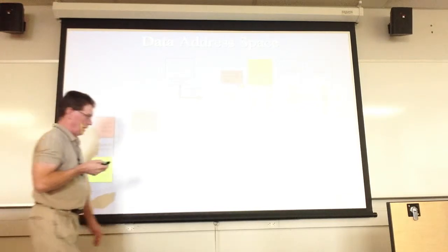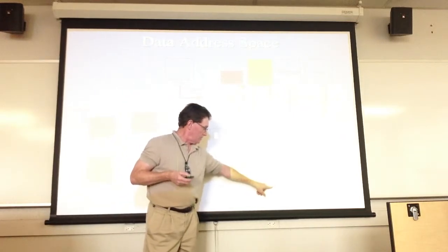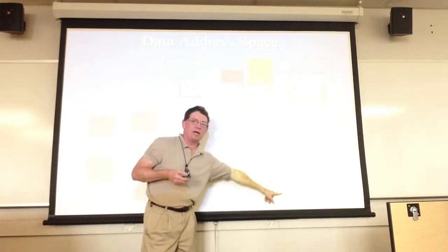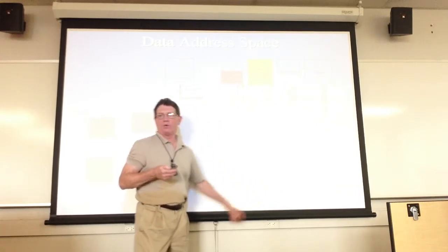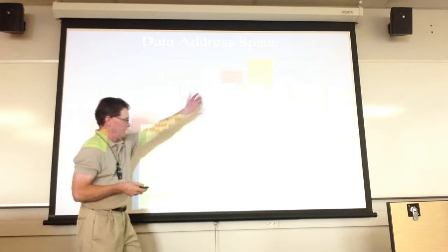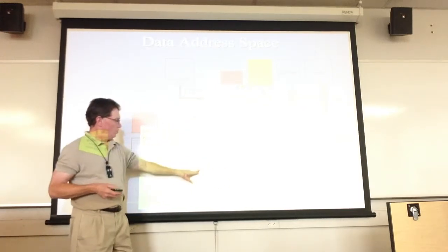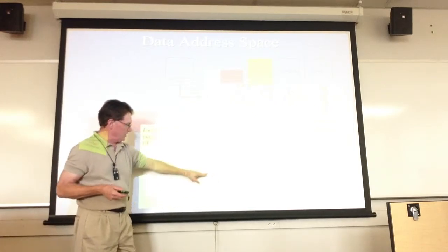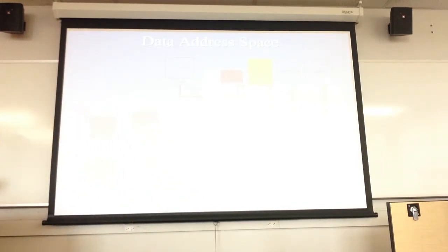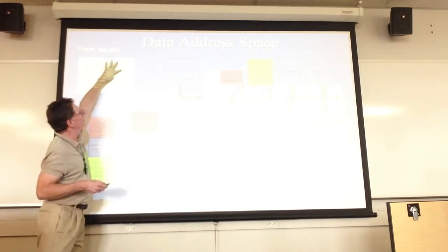Here I'm going to output. I'm going to take the contents of R12 and load it into the stack pointer high using the out. I can take the status of the status register into R15, or any one of the general purpose registers. Write a program to add the contents of pin C I/O register to the contents of pin D and store the result into RAM at 90. Here we take the contents of pin C into R20, take the contents of pin D into R21, add them together, and store that result into that memory location. It's pretty straightforward. And again, just showing you from the LSS file, these are the I/O addresses.